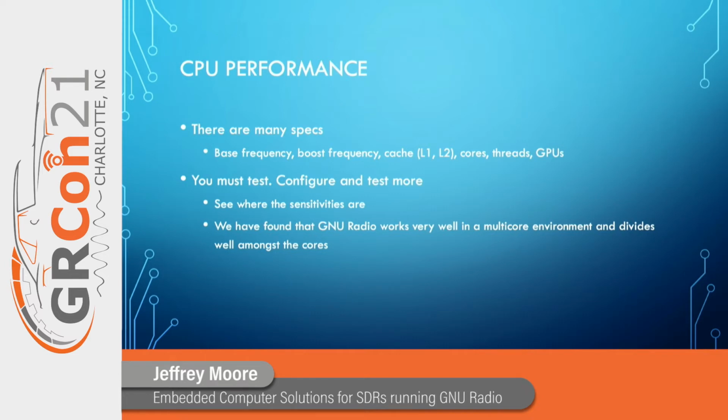So the performance itself, you can look at frequency and you can look at level 1, level 2 caches and how many threads and what the GPU is doing. But by and large, you really got to test this. Test it with your particular OS, your version of GNU Radio, and your application and see what works. We've not found any substitute for that.